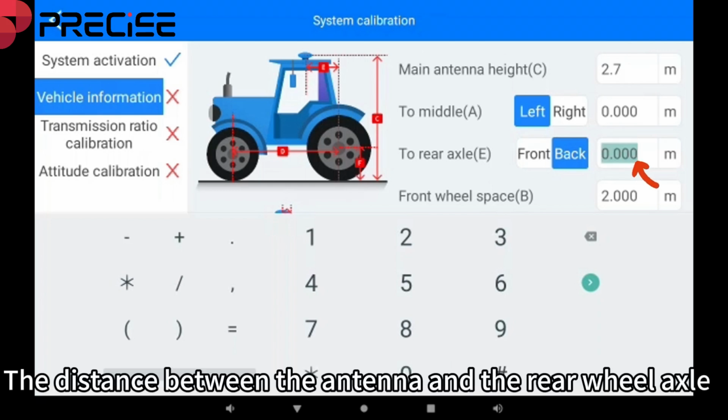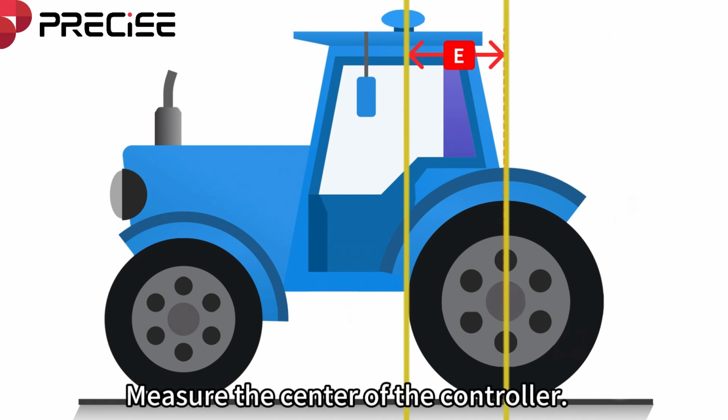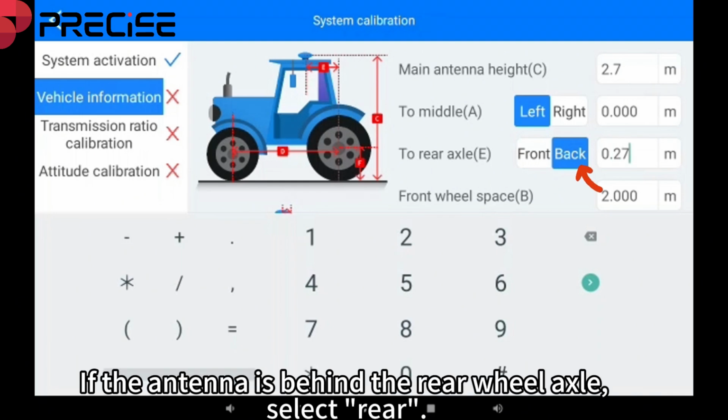The distance between the antenna and the rear wheel axle. Measure the center of the controller. Measure the horizontal distance from the center of the controller to the center of the rear wheel axle. If the antenna is in front of the rear wheel axle, select front. If the antenna is behind the rear wheel axle, select rear.